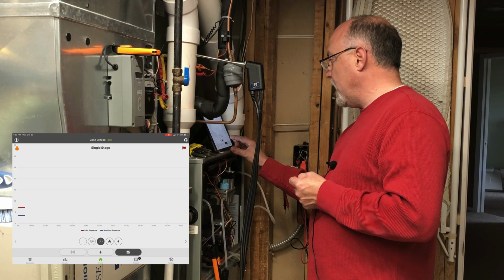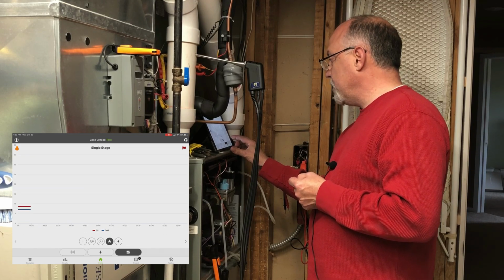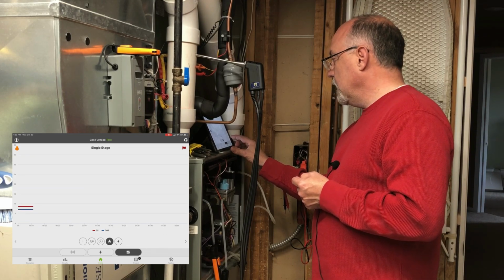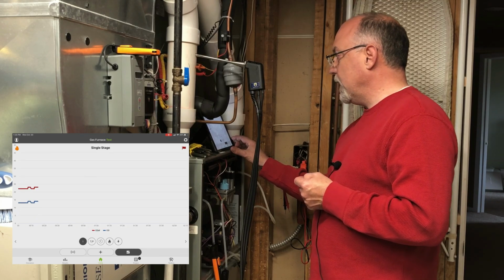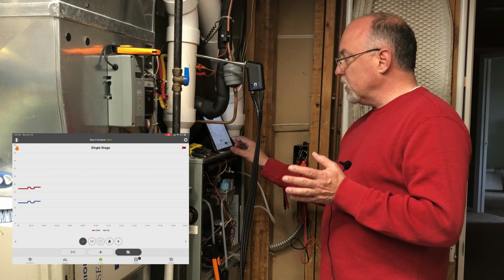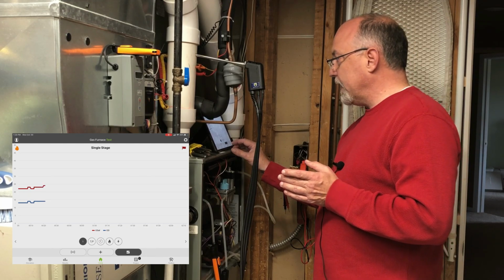Inlet manifold pressure are really stable on there. Excess air and stack temp, O2 and CO2. And then we'll go up here to net and gross, and then back to CO and CO air free. So right now, those look like they're really nice and stable on there. So we're in a good position now. I can capture my readings.